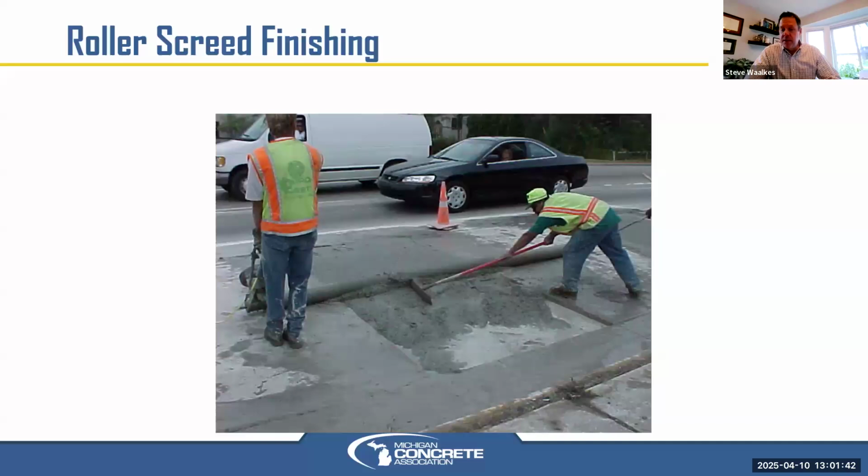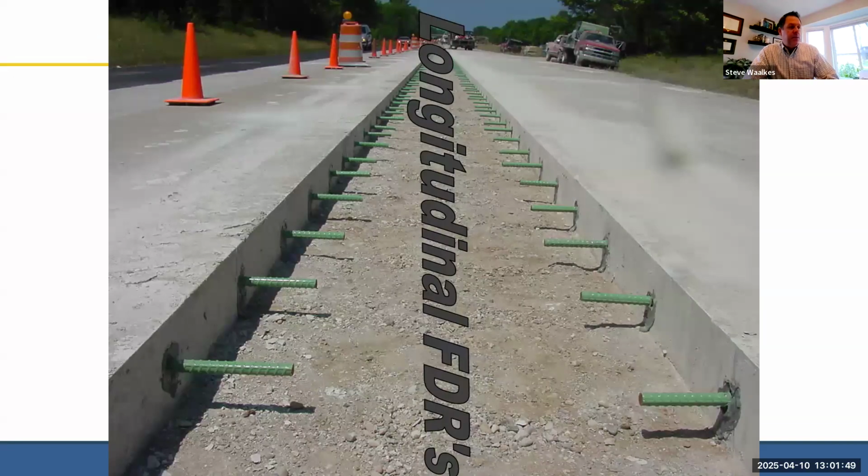Concrete placement with a single roller screed, going from the side here in this case. And then we'll real quickly touch on longitudinal full depth repairs, another common one. Here you can see a center line repair prepped and ready for concrete placement. This is kind of a newer detail. It's still in special provisions, but it's used a lot.